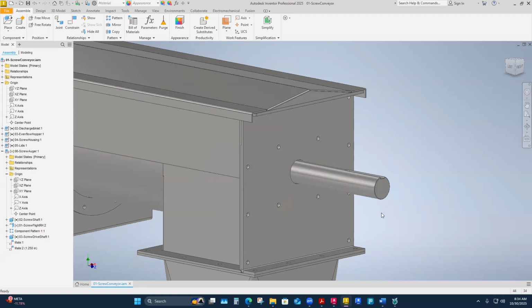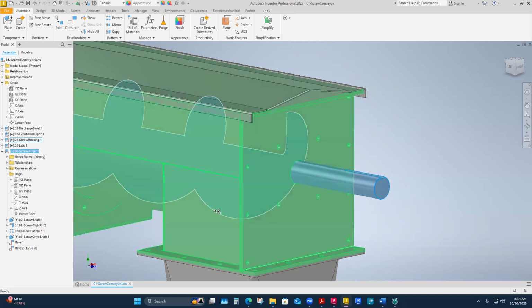So I need to know essentially what this diameter is, and the thing that's driving this diameter is really the size of my auger and everything. Like the size of my housing and how big this thing is. There's sheets that I checked out to say, oh, that's how big this shaft needs to be, because that's an engineered design that's going on here. In order for this not to break and crack in half on me, if it's too big or too small. If it's too big, the actual auger as it moves the material could break something inside. And if it's too small, maybe whatever I'm trying to auger through here will have too much torque or too much resistance and it'll break my shaft. So this had to be an engineered size.